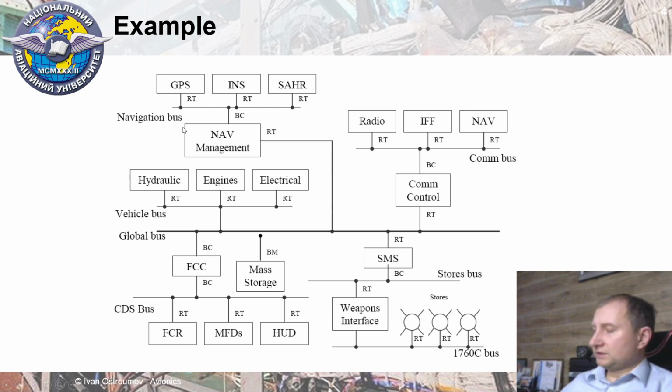Usually it is a group of avionics which require identical data. And inside of each federation we have a local subnetwork of particular line replaceable units. And then via this subnetwork, the bus controller can guide packets from the main network to the extended subnetwork.